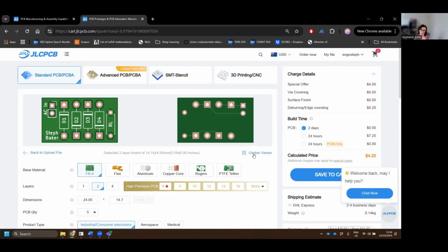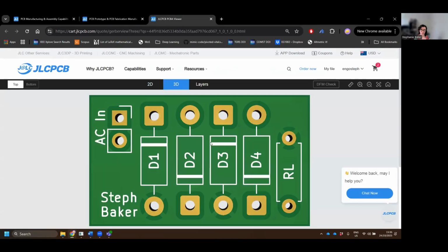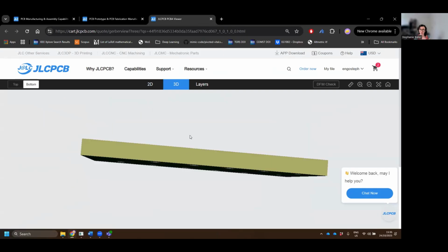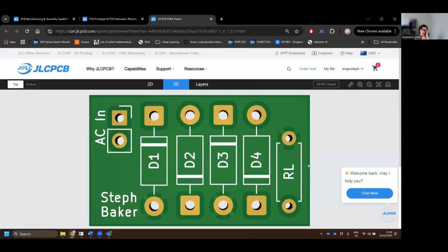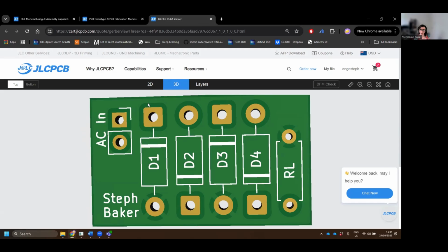So again, we can go through that same process, and I encourage you to, of going to the Gerber viewer and have a look at the 3D predominantly, so you can see what it looks like top and back. Very similar kind of to what you would do in KiCad. You can also inspect that each of the layers are the layers that they're supposed to be. So you've actually got your bottom layer, top layer, your drill files there as well. Cool. All right, so that now looks pretty believable. So what you would be doing is you'd be including some screenshots to send to the techs of the front and the back so that they can kind of believe that you've got everything ready to go, and they can more easily identify if you've not gotten it all right.